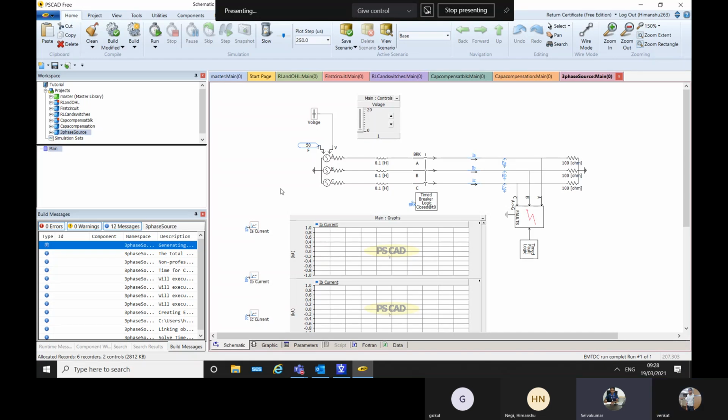My view is based on his experience and his feedback. My suggestion is that someone takes maybe 1 hour or 1.5 hours for a short circuit study. That's needed for us anyway, right? The customer will give the three-phase fault current, maximum and minimum, the single line to ground fault current, maximum and minimum, and the X by R ratio at the grid. How you put it in the grid as a source is what we are going to explain. But how to get that value, he will know only when he performs the short circuit study, correct?